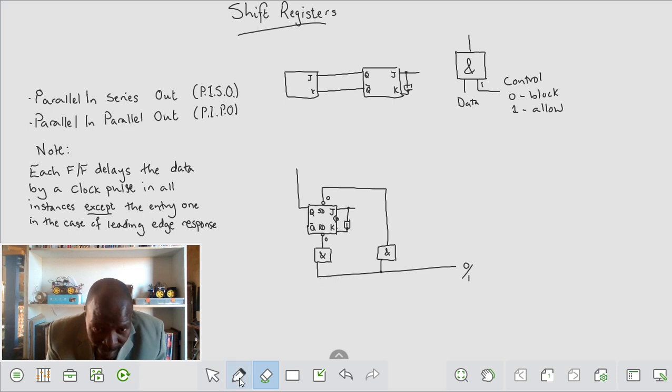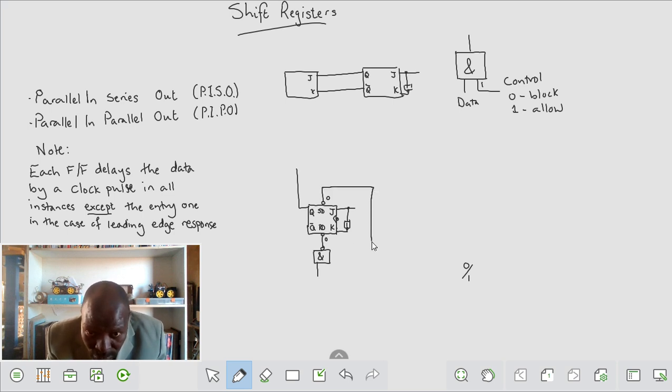a NAND gate instead. All right, so I wanted that understanding of why we are not using the same control circuit that we started with. Now why we are actually using NAND. Okay, so you see that with this one here, we're not going to use the AND, we're going to use the NAND for that reason. Okay, so there is our NAND, and there is our NAND. Why are we having two? Because we're either going to set or reset.